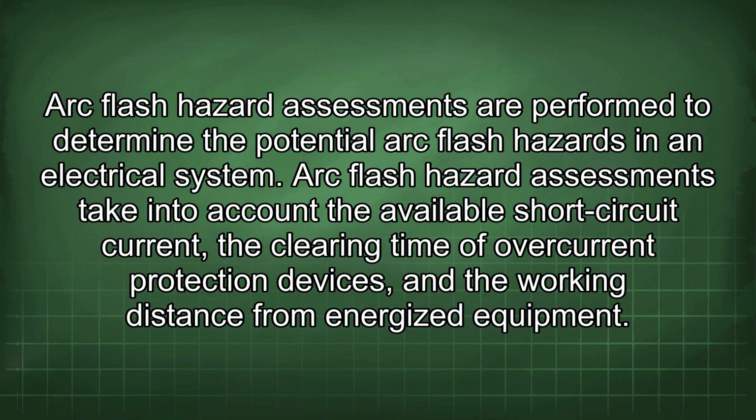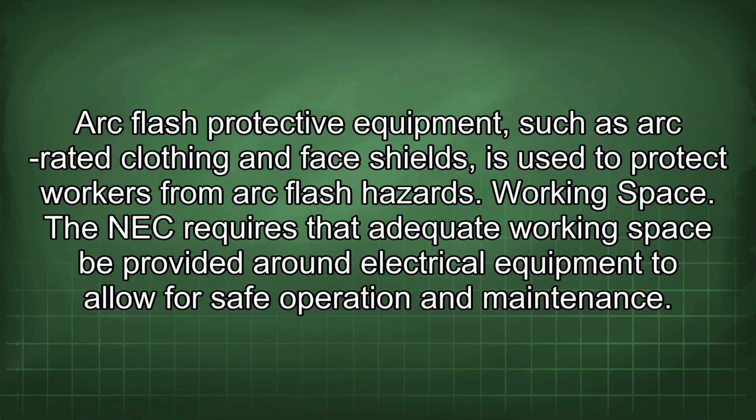Arc flash hazard assessments are performed to determine the potential arc flash hazards in an electrical system. Arc flash hazard assessments take into account the available short-circuit current, the clearing time of overcurrent protection devices, and the working distance from energized equipment. Arc flash protective equipment, such as arc-rated clothing and face shields, is used to protect workers from arc flash hazards.